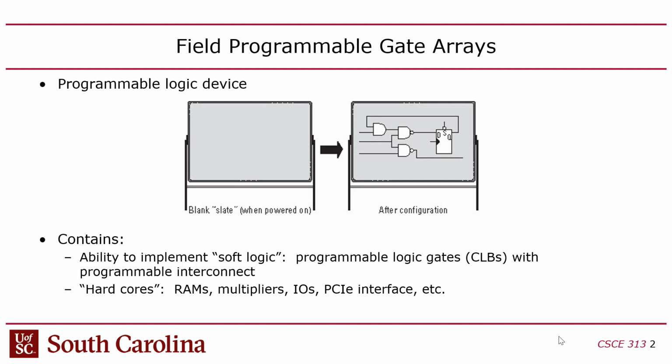And part of the reason is because it's a 32-bit processor, but it's a soft core processor, right? Meaning that it's not transistorized. It's not built with transistors. It's built with LUTs, right? FPGA LUTs, FPGA gates. So it's gonna be 10 times slower. In fact, ours is more than 10 times slower because we're only going to run ours at 50 megahertz. You guys with me? Now you might ask, how fast could that processor run? Maybe 150, 200 if we tried.